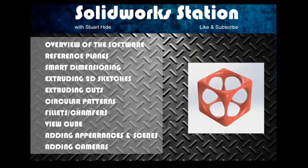I've talked to you about your top planes, your front planes and your right planes, and how to go to normal 2 and how to start a sketch. We've talked about smart dimensioning, a little bit of how to smart dimension your lines when you sketch. You can actually smart dimension angles as well, but we might do that in another live tutorial. We've looked at extruding this 2D shape. It was a 50 by 50 line drawing, and we've transferred that line drawing to become a boss extrude of 50 around the midplane. So we've looked at the extrude of the sketch to turn it into a 3D model.